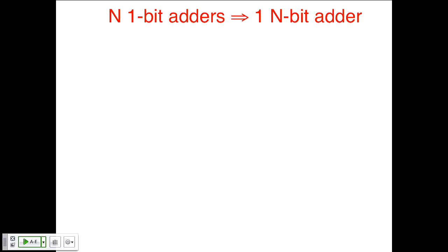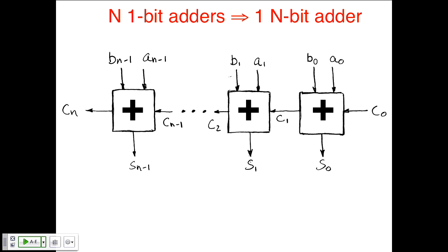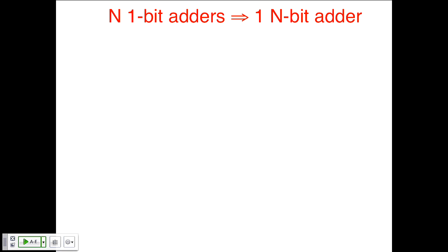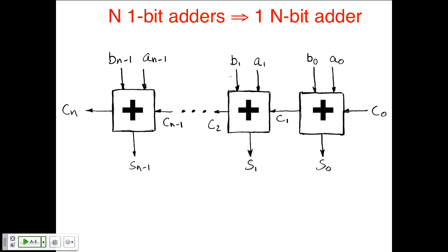If you have both kinds of one-bit adder, if you want to make a large adder, you just string them all together, right? So this is the circuitry for one adder, basically a version of this on this slide. A carry coming in, sums coming out. I'll talk about why there's a C0 here. You don't need this for an add, but we'll talk about it later. A0, B0 produces sum 0 and carry to the next one. So these are all chained together.